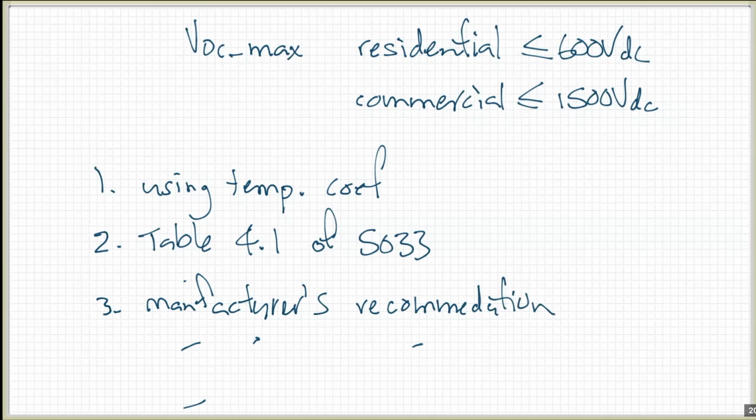Now, some questions have come in. Sean just said, did I hear right? Can you really oversize more than 133% on a hybrid or off-grid system with batteries for STC purposes? Yes, you did hear right, but, and this is the big but, you should confirm this with the entity that creates your certificates, because they're the responsible entity. So if they're happy to create certificates on a hybrid system with 150% oversizing, then of course you can do it. So just check with them first before you go ahead.